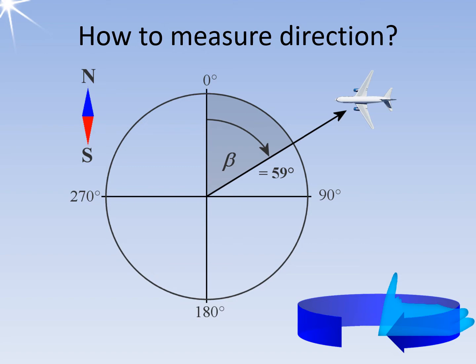A determination of the side and height angle of the target is possible by the bundling of the transmitted and received energy by the antenna. The angle measurement is made possible by the fact that the antenna must point exactly in the direction from which it receives the echo signal. These angles can be measured as elevation and bearing angles at the antenna turntable.